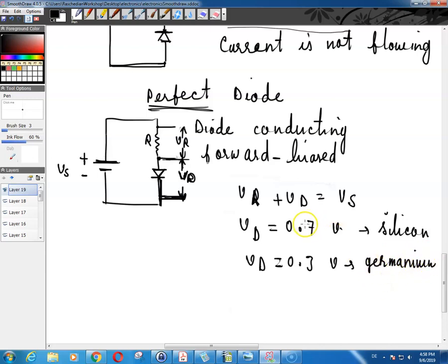That is for the germanium diode. And of course, when you practically breadboard this circuit, or actually have some physical power supply, some diode and some resistor connected together, if you measure this voltage, it's somewhere around 0.55, 0.6, 0.7. Depending on the diode, the voltage drop changes, but it's always somewhere around 0.7. And that's basically why in calculation we always take this value to be 0.7 volts.